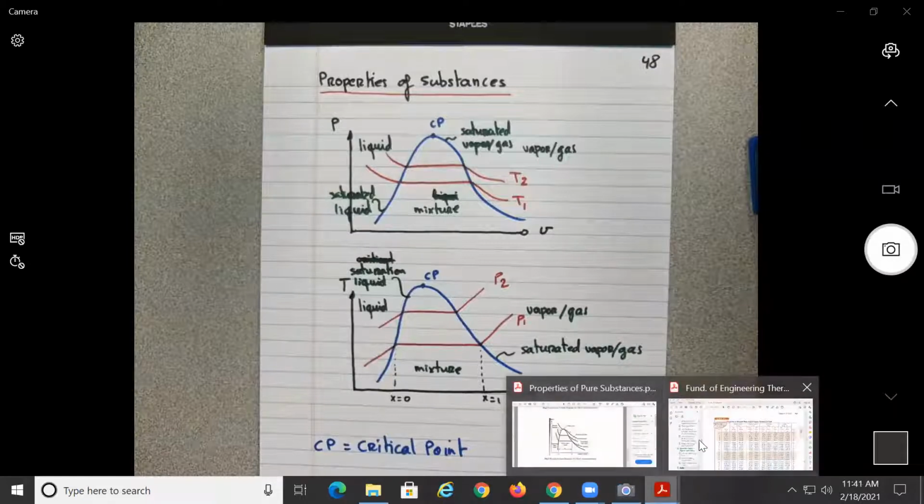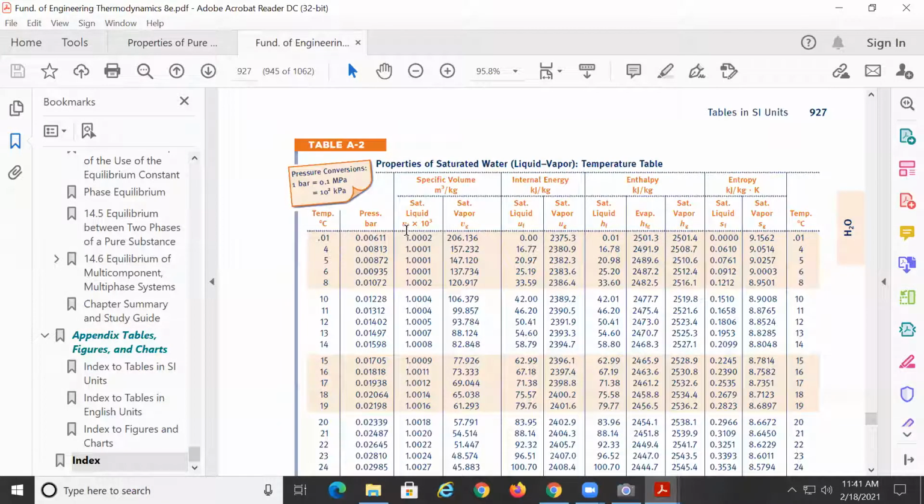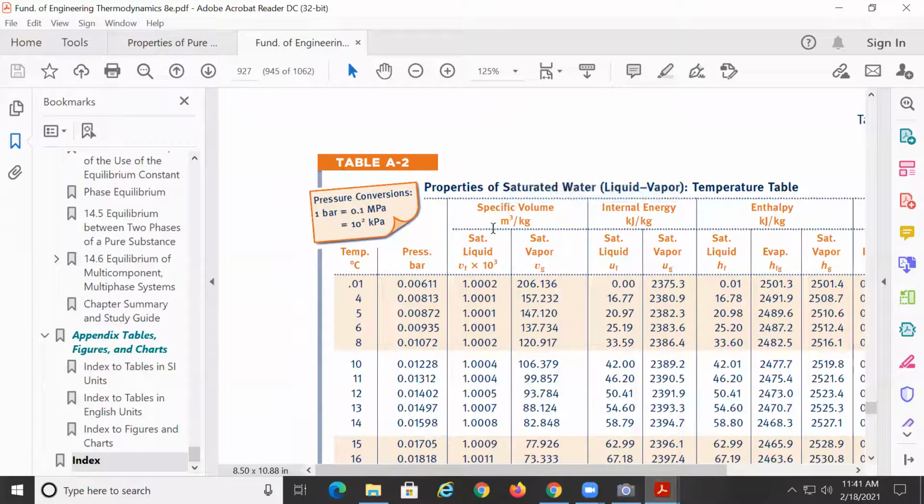And that's what you have over here. For fluid, they put an f. This is something confusing, but I think if you use your logic, it's a lot easier. I will explain now what it means. v sub f means it is all liquid. v sub g means that everything is gas.